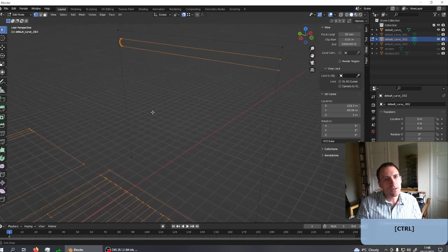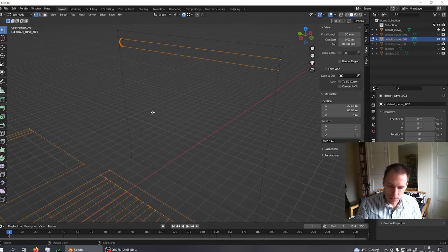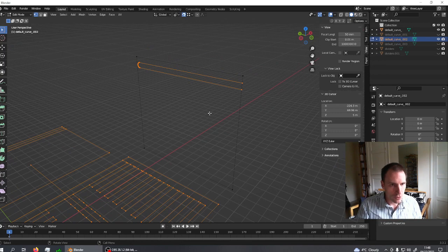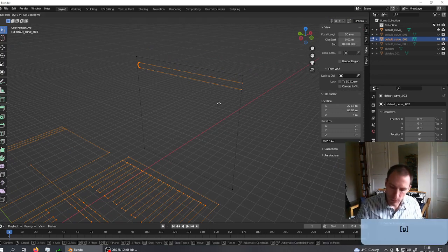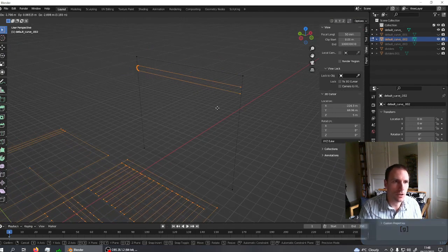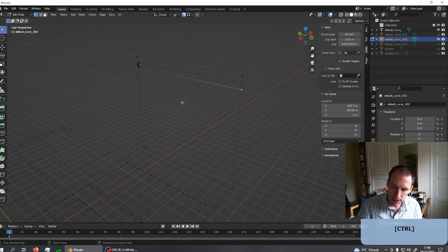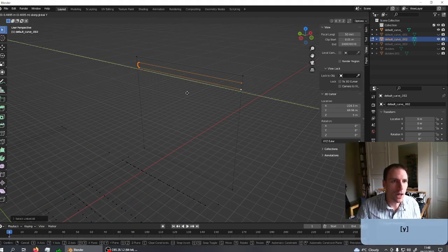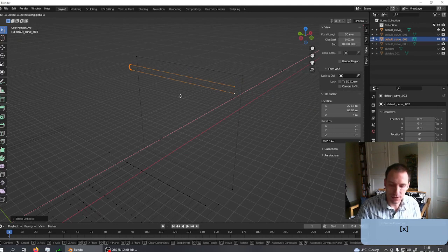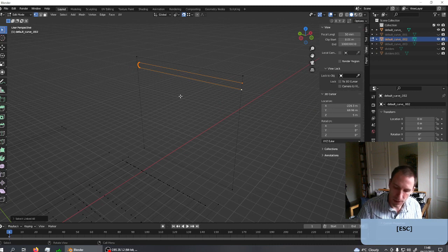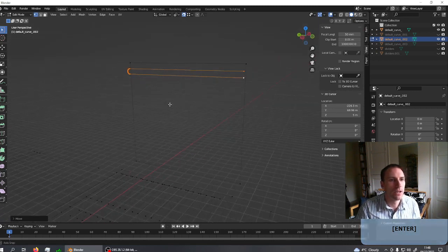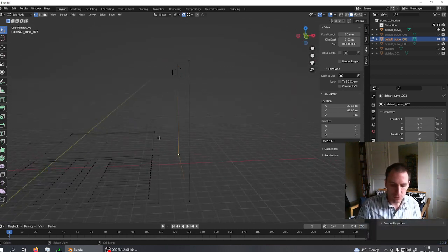A couple of ways we can do this. Let's go for grab. And then we just say we want this to be fire. Let's go for 6mm high. We've got all of those. Control L for link. Grab. And then Y or X. Let's say we want to go 6mm out. G -6. Depends which way you want to travel. There we go. And then that leaves us with that one.